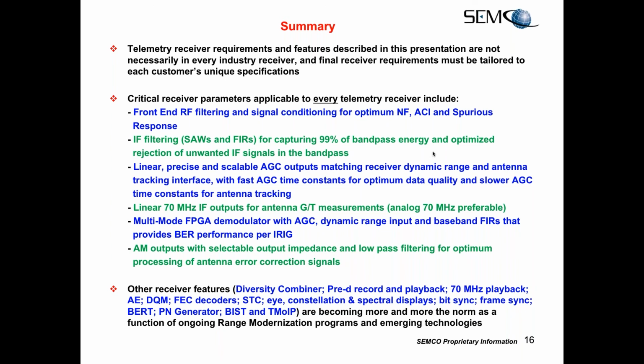Thank you so much. Another question from the audience is in regards to your built-in self-test. Does the built-in self-test have an output? Is the output power adjustable? You can route the power output, but it's at a fixed level right now. We basically have it at a fixed level for internal BER testing internal to the receiver.